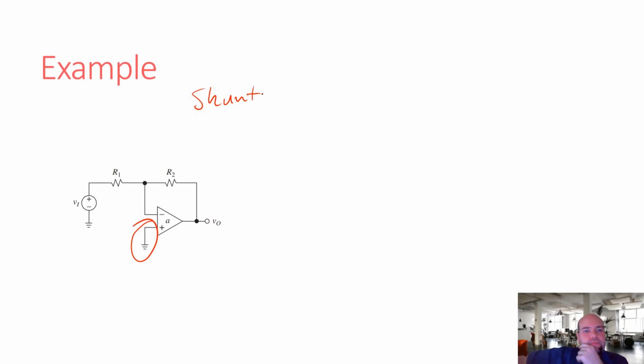And what about the output? Well, if I connect a load here, if I change this output load, does my output voltage change? No. So we are sampling the voltage.